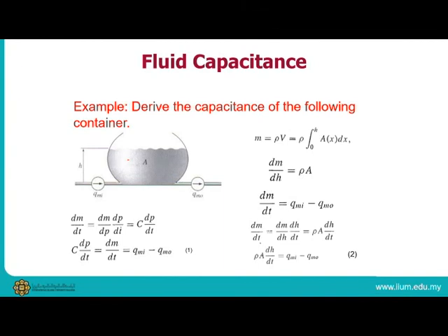Okay, so now we look into another example where we have a container here. We need to derive the capacitance of the container, and from here we know that the volume for this container is equal to the integration of A x dx from 0 to h, right?